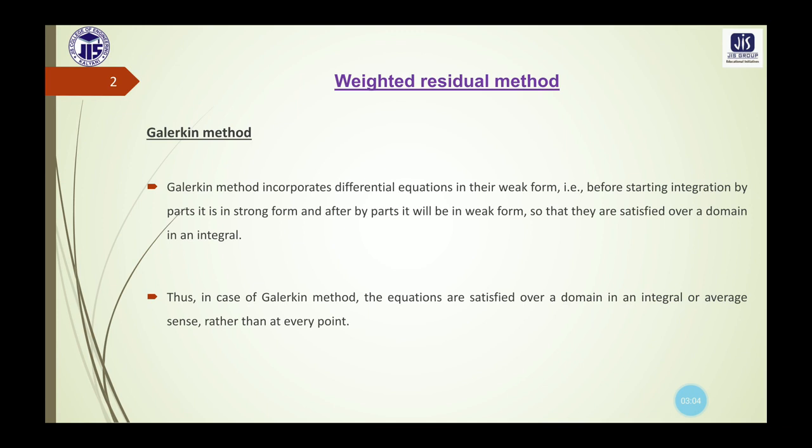So what are these three different methods of engineering analysis actually? Number one is the experimental method. So in this experimental method, actually we use the prototype. Now if we want to change the dimension of that prototype, we have to actually disassemble the entire prototype and again reassemble it, and then the testing will be carried out. So this type of experimental method or experimental analysis needs manpower and material. So that means it is actually time consuming and costly also.